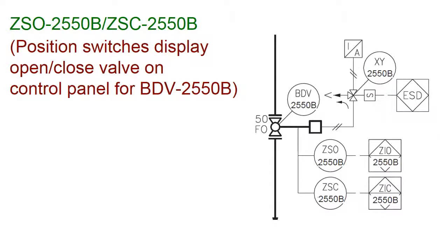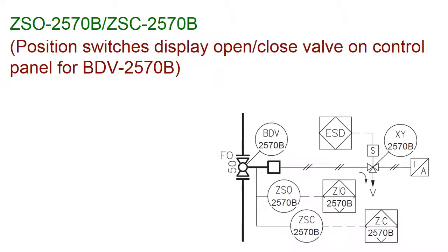ZSO2550B, ZSC2550B. Position switches display open/close valve on control panel for EV2550B. ZSO2570B, ZSC2570B. Position switches display open/close valve on control panel for EV2570B.